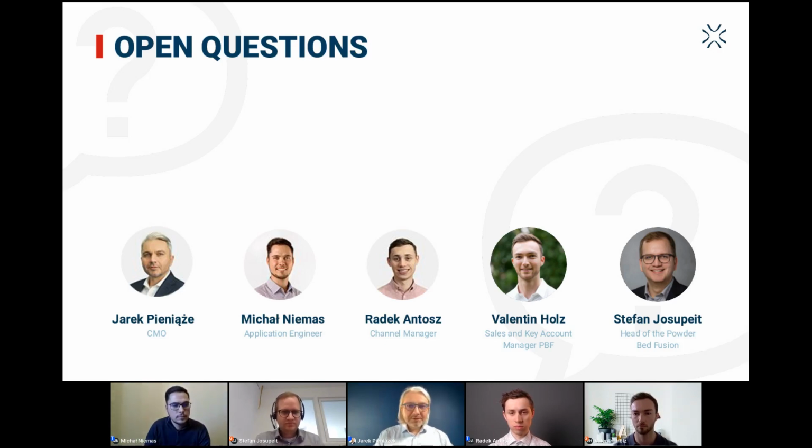Okay, thank you. That's a really good question from Marcelo. Is it possible to achieve smooth and shiny surfaces with PA12 with some chemical or mechanical post-processing? Basically, as was mentioned before, it's possible to do some smoothing, for example vapor smoothing. There are different companies which are doing vapor smoothing. So it's possible to make a shiny, glossy surface for nylon parts.